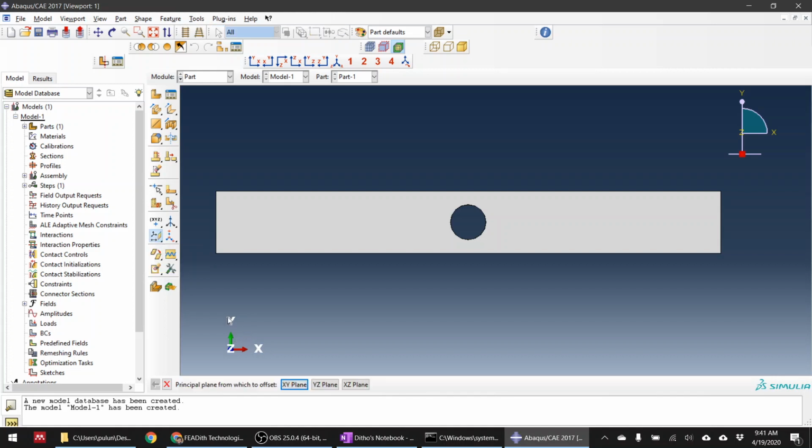So I want to make a datum plane here. This is the YZ cutting plane, right? Because this is Y, this is Z, YZ, and then I offset maybe around 90. Yeah, 90 maybe enough. Yeah, good. And I want to make another one, YZ. The offset now is 110. Okay. So now I have two datum planes.